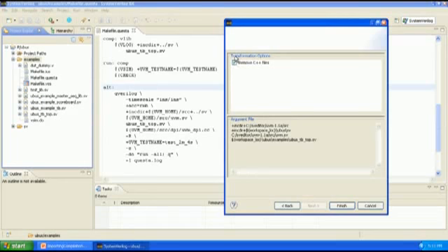And we also have some options here for transforming the argument file. So, for example, there was initially a C++ file listed on the qverilog command line. We actually don't really want this, so we'll filter that out by selecting the Remove C++ Files option.